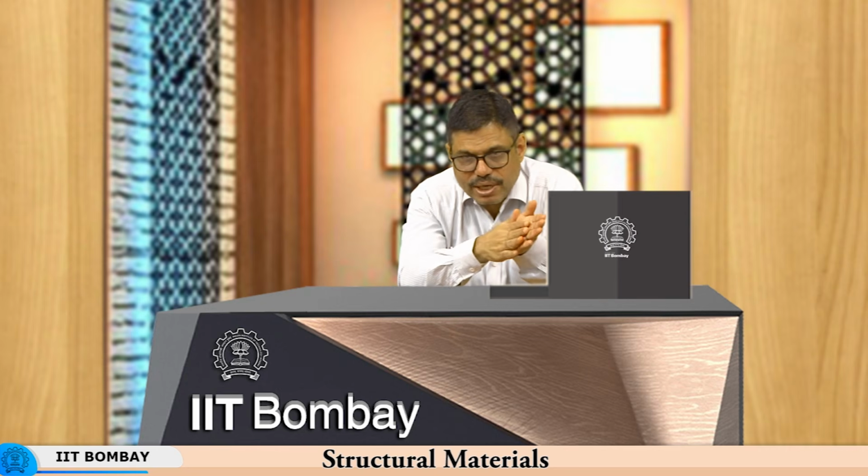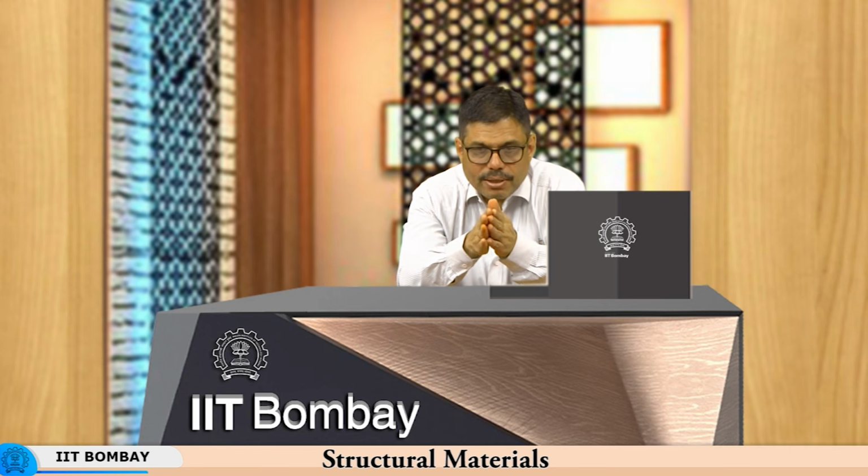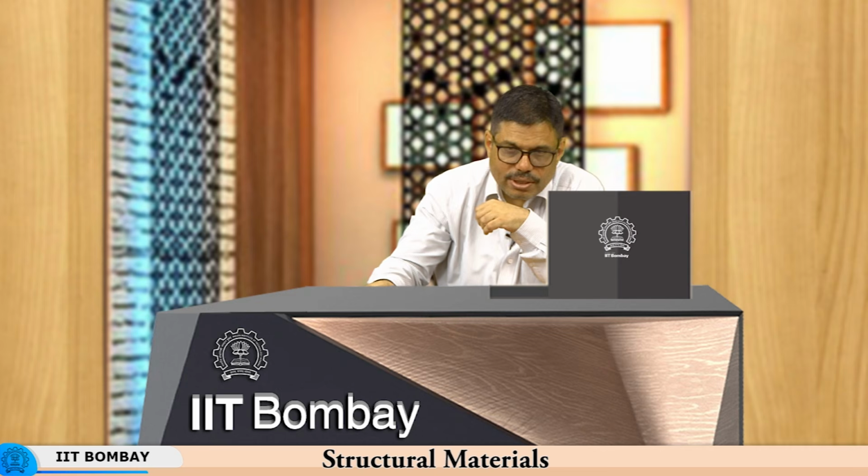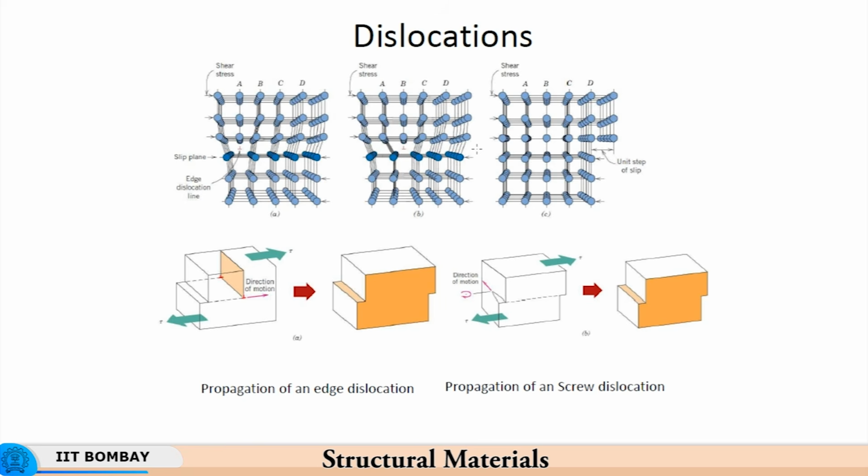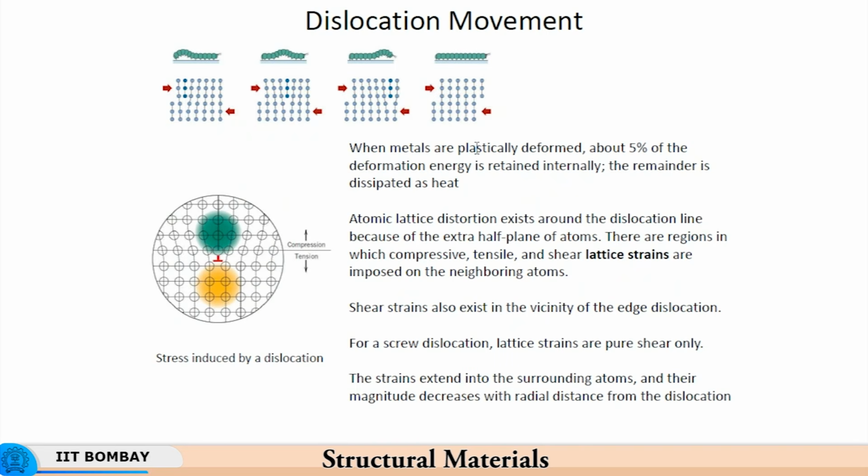So once the dislocations have started moving, then as you see the creation of the step, the dislocation movement results in a permanent change in the shape. So now this slip of this workpiece in this plane is now permanent. So these 2 steps have been generated permanently. So basically what we are talking about is dislocations facilitating the change in shape of the material at a much